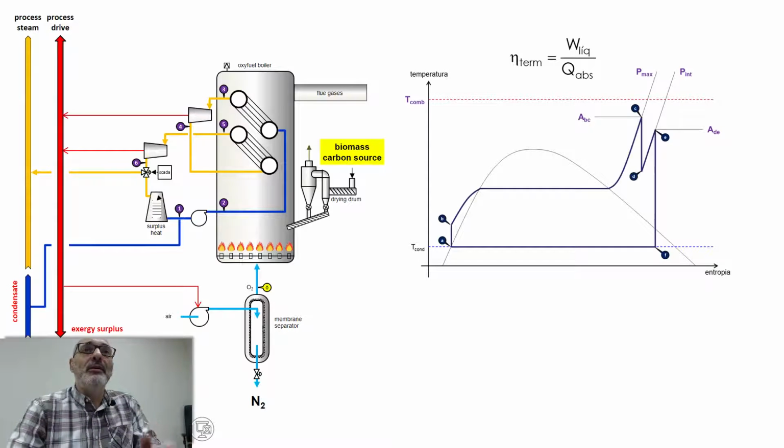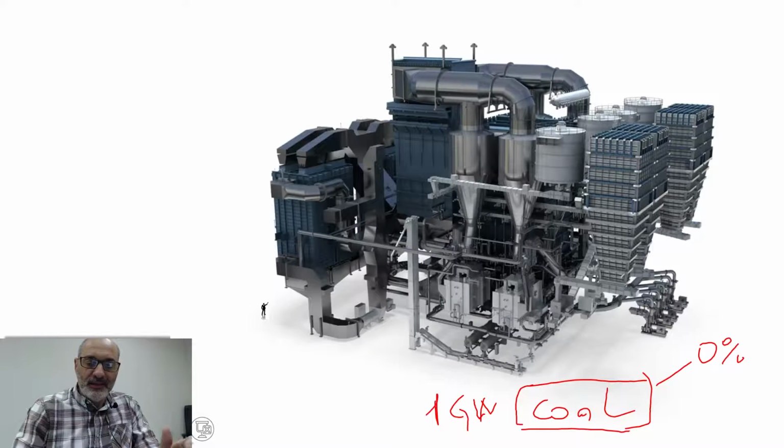And what I'm going to show you right now is because, as I said, coal virtually has no water, no humidity, and biomass typically has 50 to 70% humidity. You can figure, let's say, sugarcane bagasse after the last mill, it is around 50% humidity. Okay, so humidity is a problem as far as burning. You're concerned with the burning operation, but as I'm going to show you right now, it's very interesting in terms of how you control the combustion temperature.